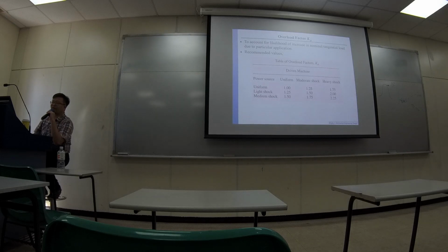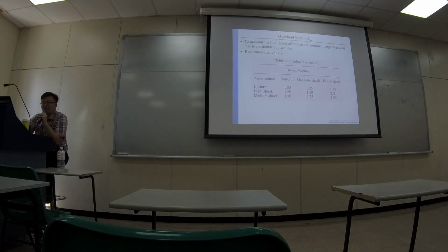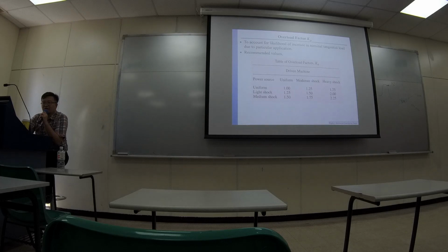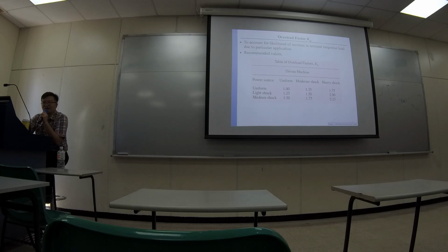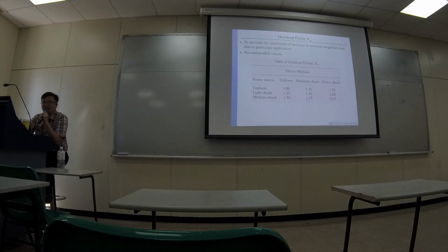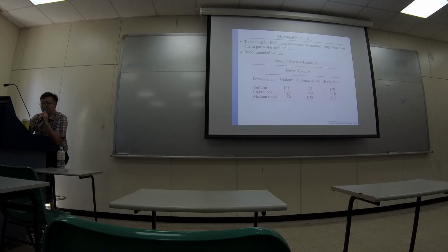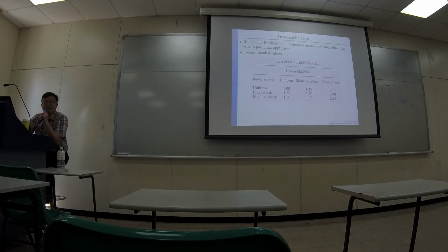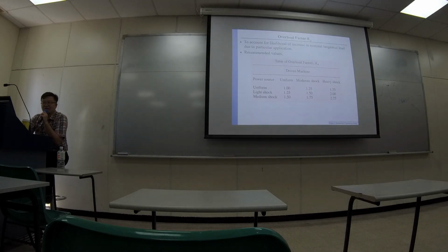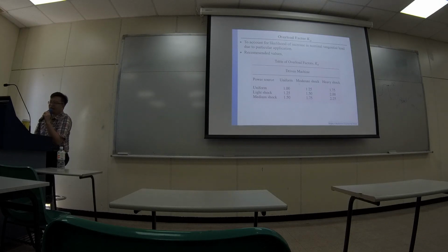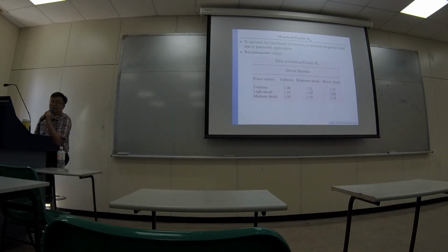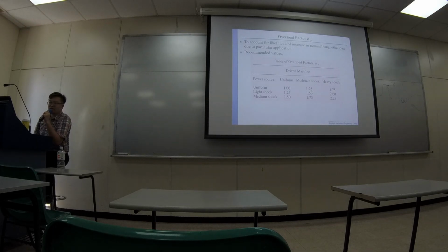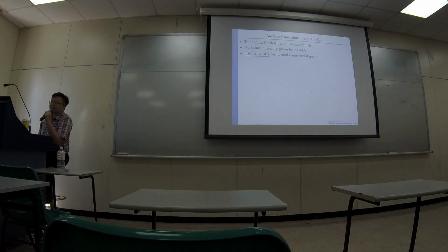So usually, whatever factor we apply, that will make our stress values larger. It's just like a stress concentration factor, but it's not about stress concentration. It's about how much stress could be applied to the component. And by this table, at this level, there's 1.25 times greater stress applied to the teeth. That's the idea. Okay.